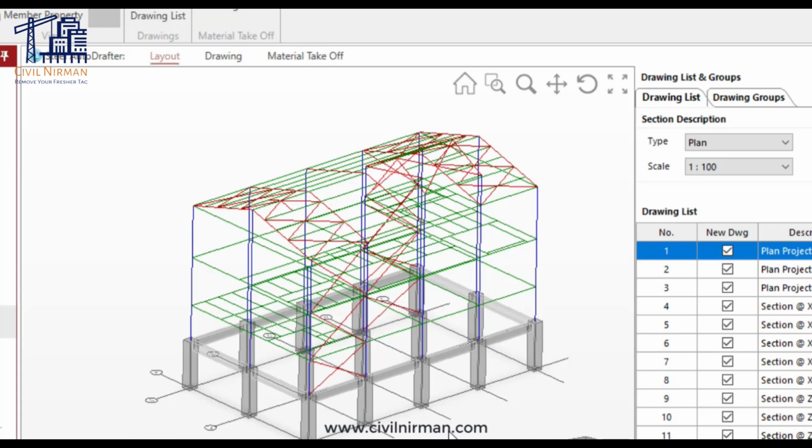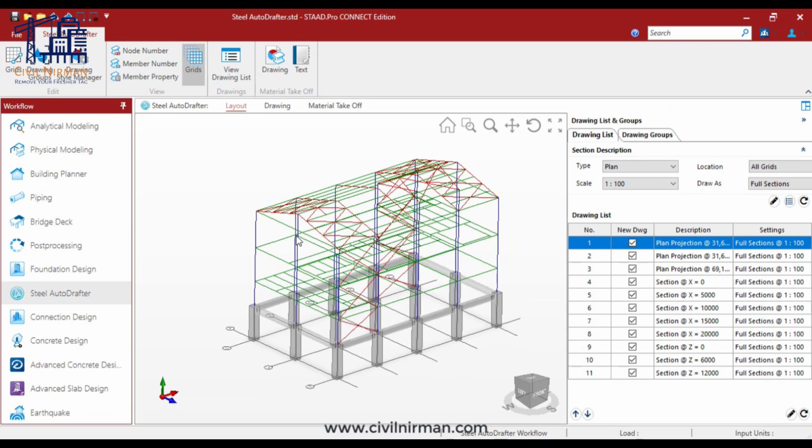Now the next most important task that you need to know is projected plans. Now see, projected plans can be used to draw plans that exist on a sloping plane. So currently I am talking about this sloping region. See, for the rest of the elevations you can simply create your plans from this particular location, but for the elevation portion there is a separate specification called plan projection.